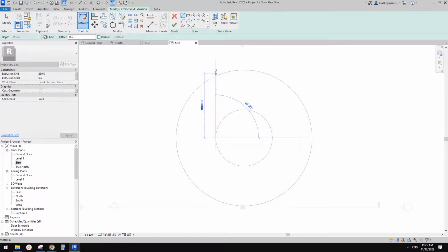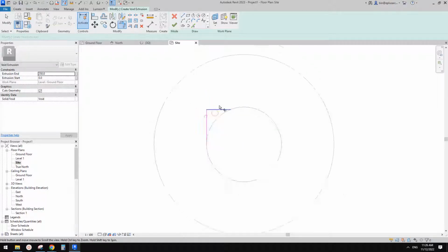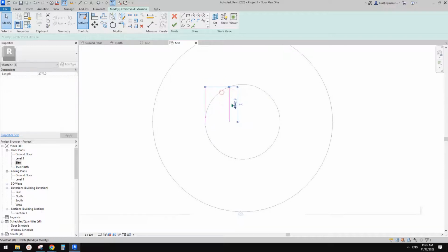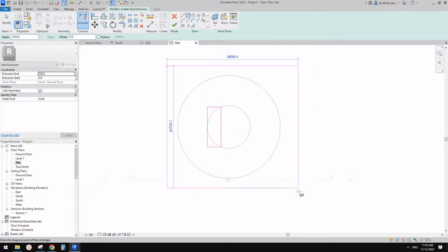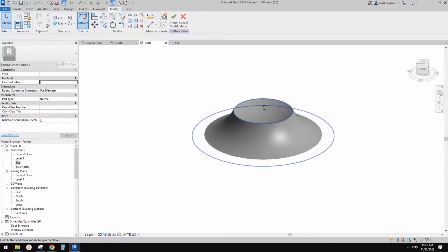And this is it. So if I go, this one should stop here. So I'll just draw this line, and for this one it will be slightly off this point, so maybe here, and a trim. And we just need to copy this one to here, and then mirror (DM), trim (TR), and just draw another big one to cover everything, and then finish, go to 3D view.